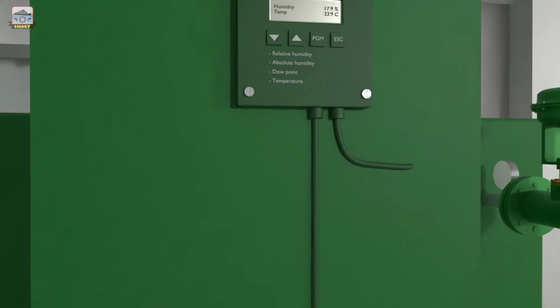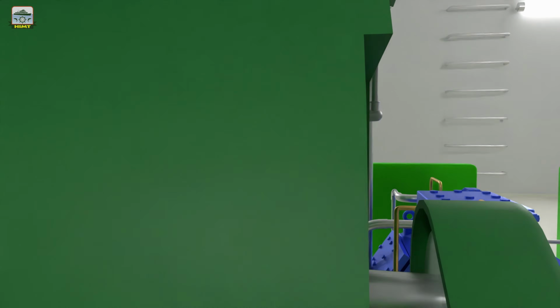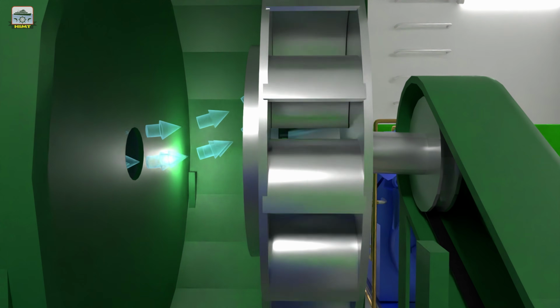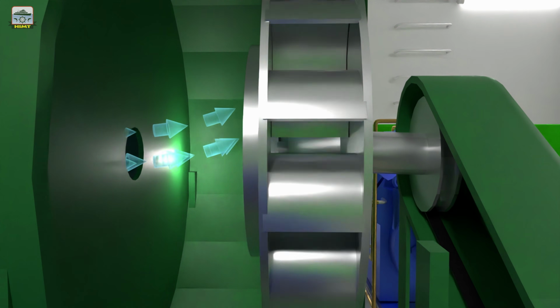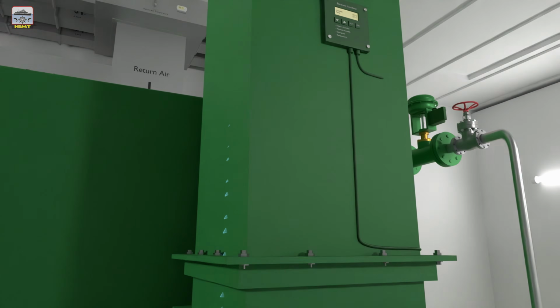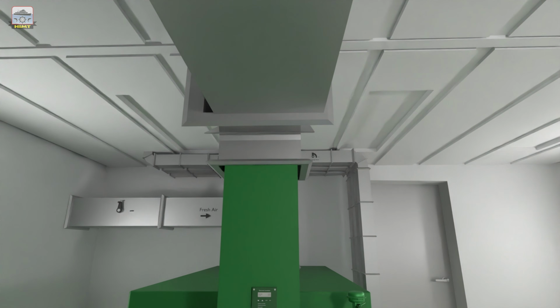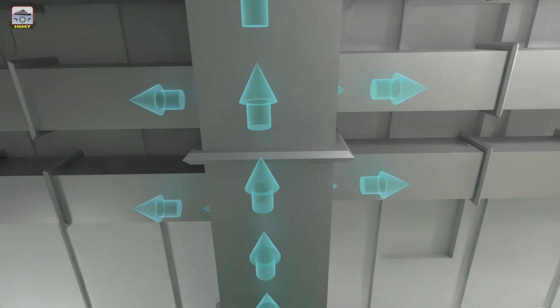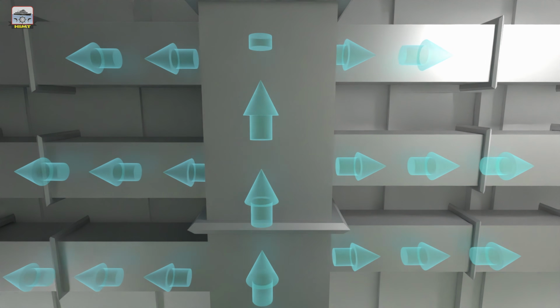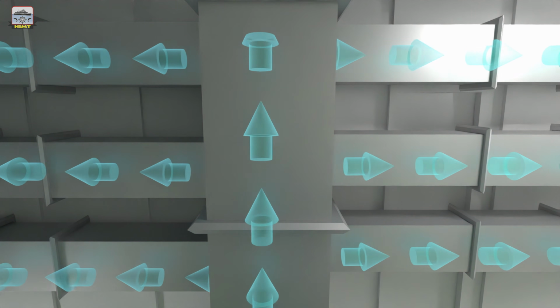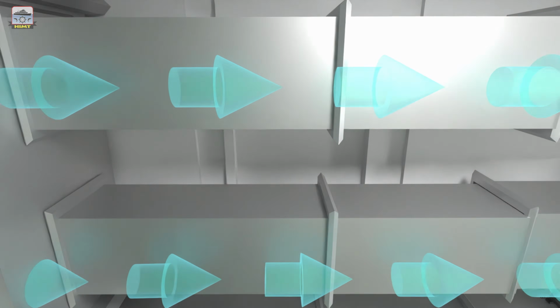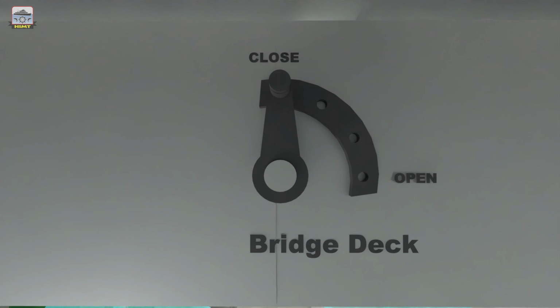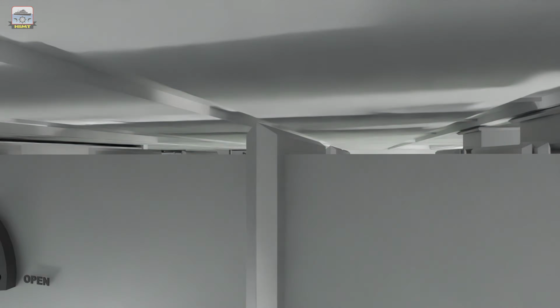The air is drawn through the air handling unit, brought to the required condition of temperature and humidity, and sucked by the ventilation blower and discharged through a ventilation system to all the rooms. The ventilation duct is a low-velocity single-duct system. The big ventilation duct in the discharge side branches into various small ducts, so that each duct is supplying the air condition to each deck. Each branch is provided with a damper to isolate a deck from supplying air, to prevent fire from spreading through ducts.